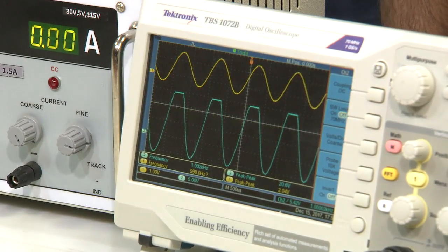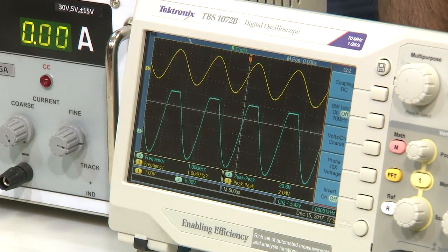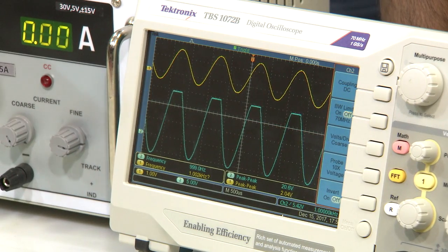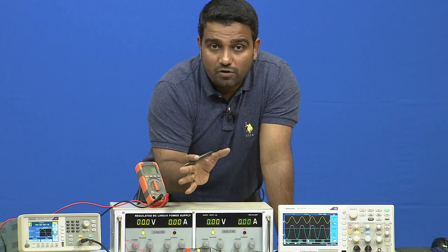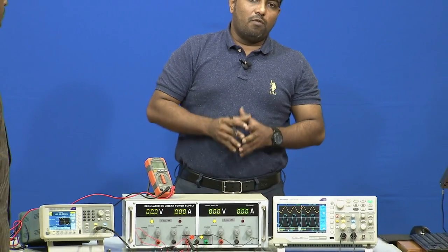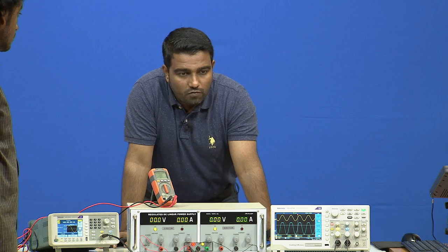The clipping is because the output is more than the bias voltage, that is what I have told you earlier. One single op amp cannot amplify infinitely, or it can amplify infinitely, but it has to depend on the bias voltage. So, bias voltage is extremely important when we are talking about the amplifier, alright. Without that it is not useful.